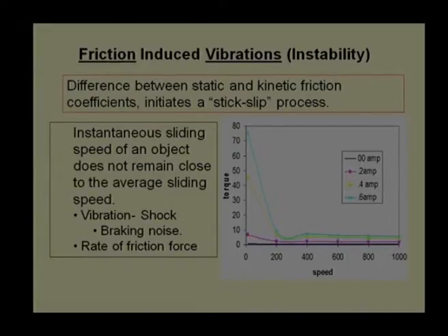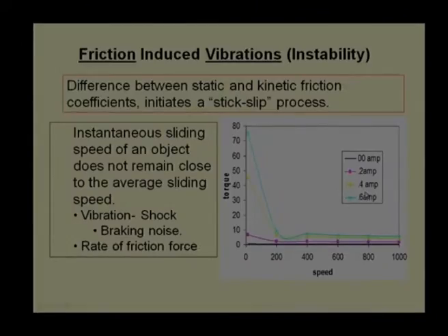At 0.2 ampere, some magnetic field was generated, which churned up the liquid, converting the particulated liquid to a semi-solid with low shear strength. When you apply a current of 0.4 ampere, it turned out to be a moderate level, and at 0.6 ampere it was very high, with good torque resistance capabilities.